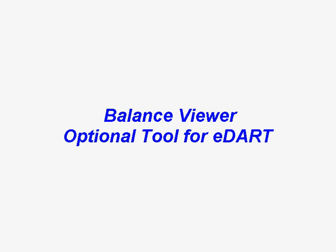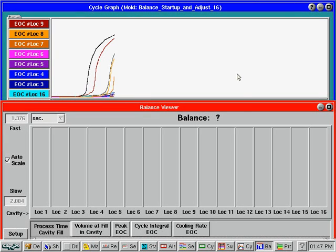This lesson shows how the balance viewer can help you adjust hot runner system balance using in-cavity sensors. It also gives you some examples of how to solve problems with it. We'll cover balancing a tool at startup with cavity pressure, then do the same with temperature sensors, and then detect an out-of-balance condition. Note that the cycle speeds for these frames are not to scale but adjusted for the pace of the presentation. Let's begin with balancing at startup.